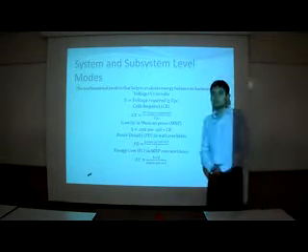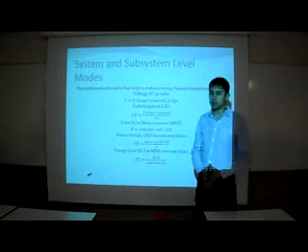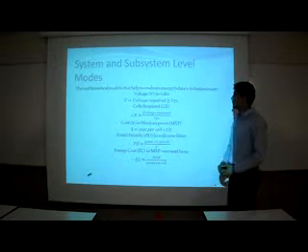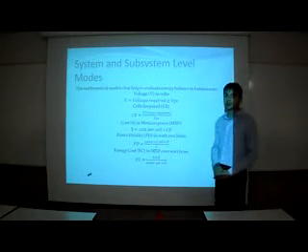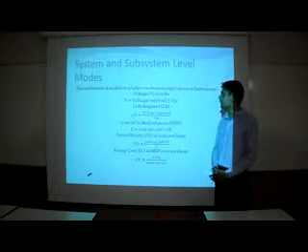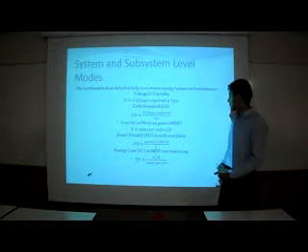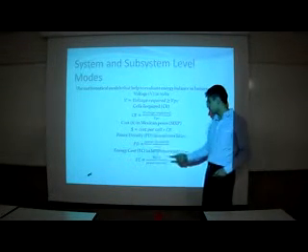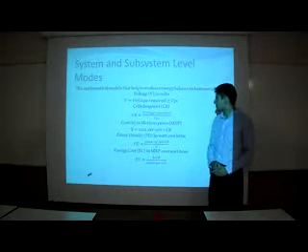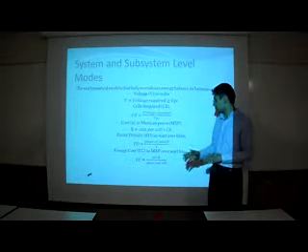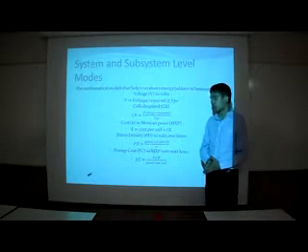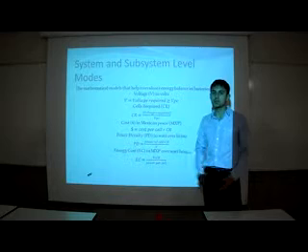And now the problem is how can we come to a decision on a battery. We made some mathematical models to help us select one of the batteries. The most important things we found were the energy cost and the power density, based on the power of the cell times the cells required over the volume of the total battery.